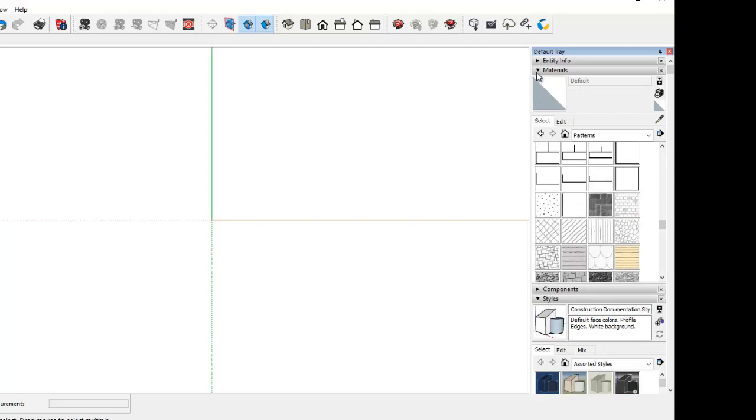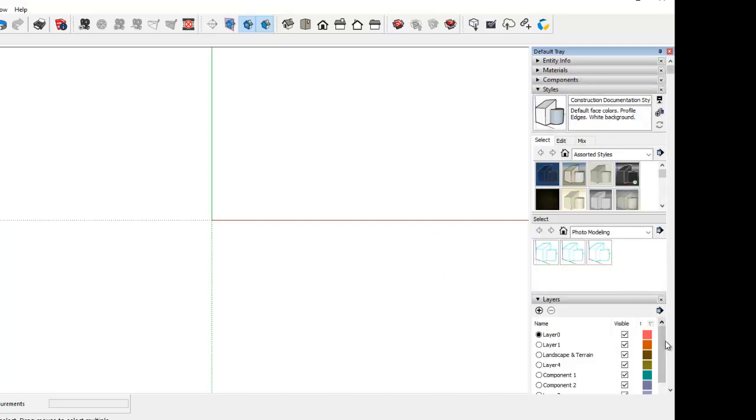We're not being prescriptive over this, but what we are being prescriptive over is the use of layers. I'm always horrified the fact is that layers aren't used, and some people didn't even know that SketchUp has layers. So by clicking on the plus button, we can add a layer. We can click onto it. We can rename it.